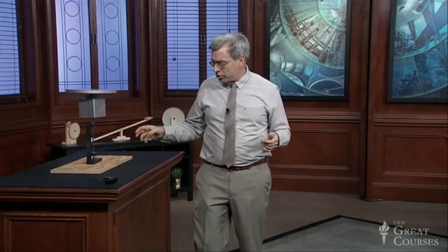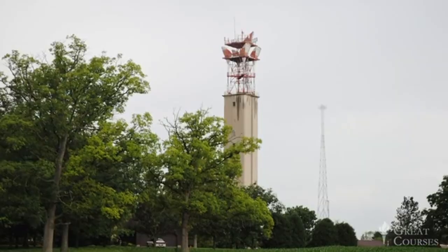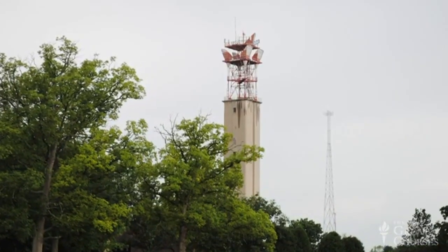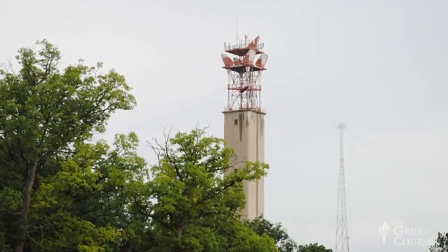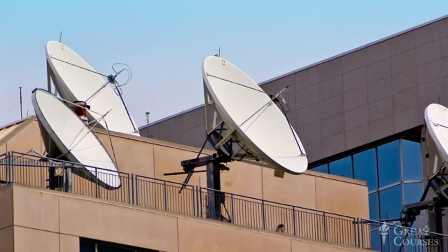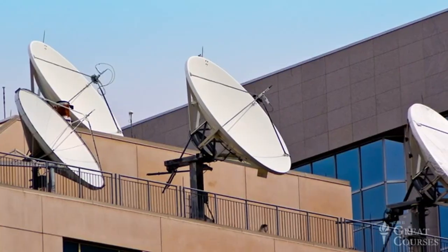At the other end of the transmission, the process happens in reverse. The electromagnetic waves impinge upon the receiving antenna, introducing a corresponding electrical current. This signal can then be demodulated to retrieve the transmitted information. Now, antennas can be designed to transmit and receive in all directions, like this one on my walkie-talkie. Or they can be designed to focus electromagnetic waves in a particular direction, as we saw with the directional antennas used on microwave relay stations last lecture, and as we'll see with parabolic satellite dishes in the next lecture.